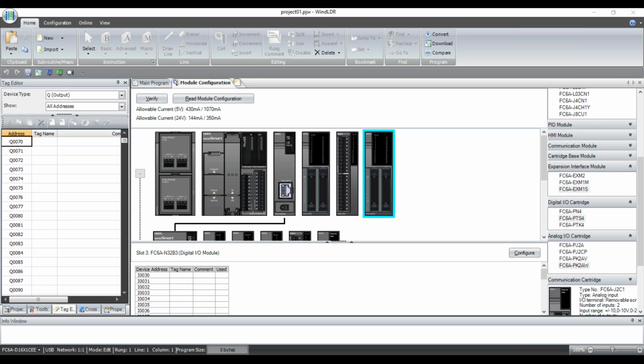On the FC6A Plus with a max of 63 I/O cards, if I use all 32 I/O modules, are we still able to use 63 cards? We are not limited by I/O. I have not tried that, but I believe that is the case. I will try that and find out. But yeah, the only thing I know of is the limitation is based on the total number of cards if you're doing the master-slave configuration. I'll try that out, and I'll answer that in the Q&A document.